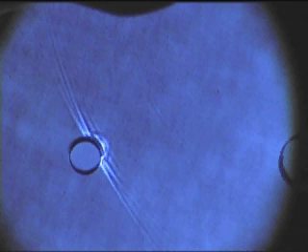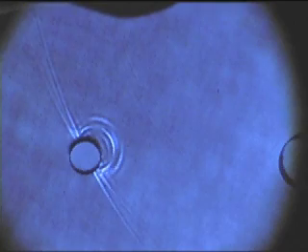As the plane wavefront hits the glass-air interface, the reflection process begins. The first point of contact occurs such that the incident shear wave makes a perpendicular incidence at the closest point on the hole surface. This will result in a maximum reflected pressure of a shear wave moving directly back along the incident path. As the incident plane wavefront of the shear wave advances, the angle made with the rounded surface of the hole ensures that no other part of the plane wavefront can be perpendicular to the hole surface. Therefore, all other points of the shear wavefront impinge at angles greater than 0.